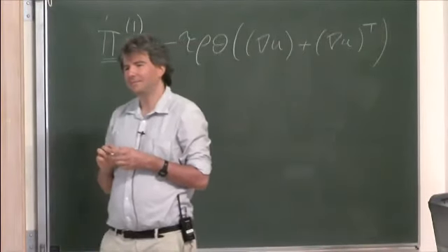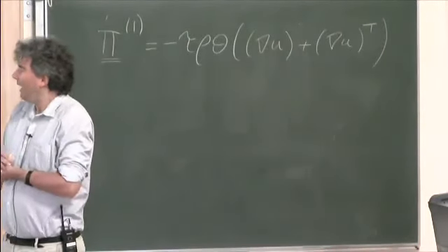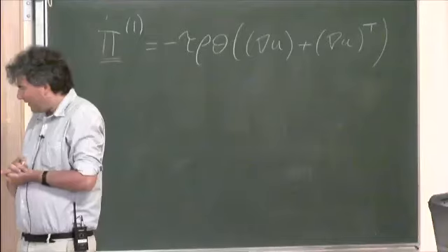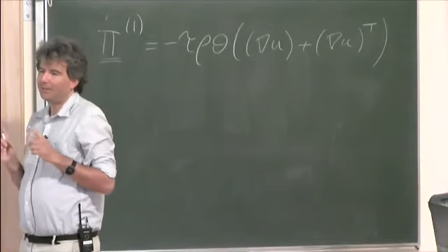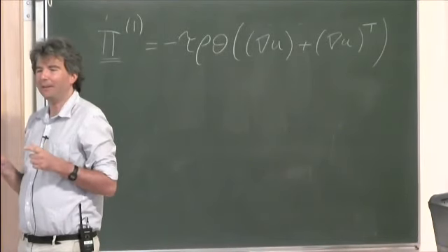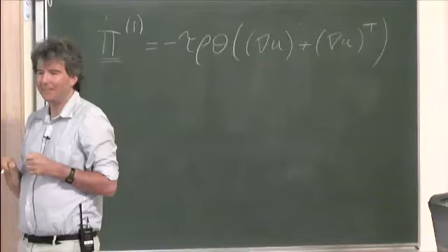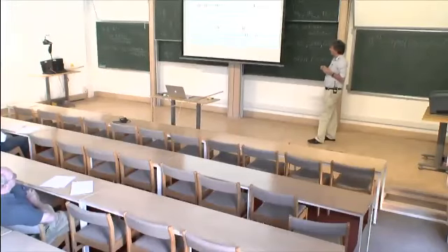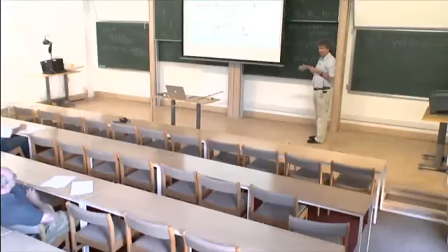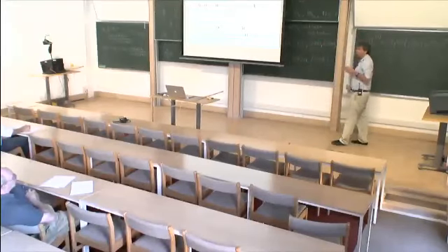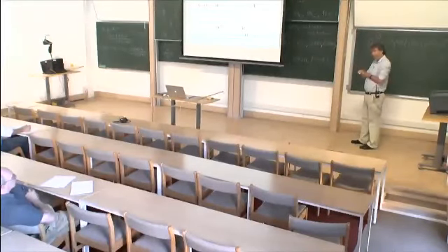When was this implicit treatment of the collision operator introduced? This formulation is from 98, but it's mathematically equivalent to what everyone was doing before then. So what you can do is you can start out with what looks like a forward Euler discretization, and you start expanding out the discrete scheme in Taylor series, and you find that you can remove a truncation error and collect it into the viscous stress, and that tells you the way you should have had a discrete collision time, call it tau discrete.